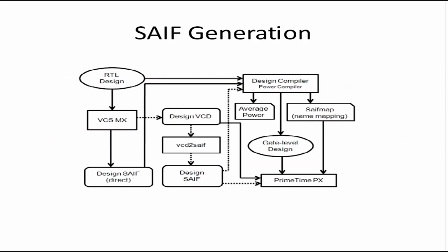So this is the flowchart. RTL design, VCS MX is a simulation tool from Synopsys. It can directly dump SAIF for you, or you can run through simulation. If you use any other tool, you can dump a format called VCD. You can use a utility called VCD to SAIF, again from Synopsys, and it will dump a SAIF file for you. In any case, you need a design SAIF file. You can plug this SAIF file back in.